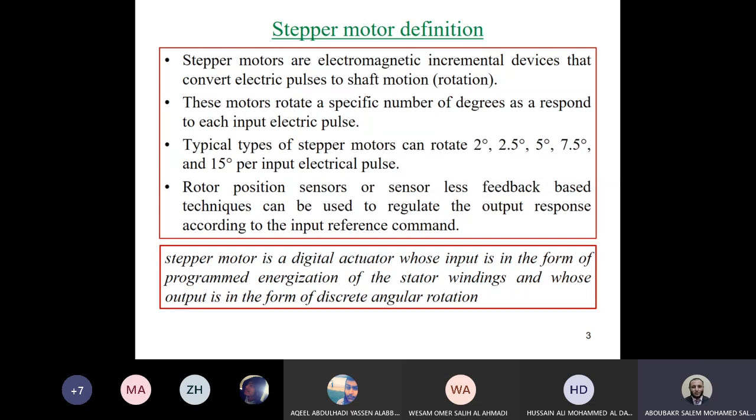So this is the difference between what we need in this application and the previous motors that we have already discussed. Actually, the stepper motor can do that. A stepper motor can work in steps, and also during standstill, the machine holds the load torque, so we can use it in such applications. It is used a lot in robots, in printers, and in a lot of applications we are going to describe in detail.